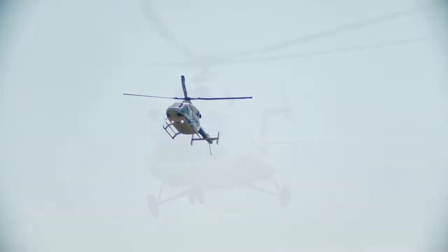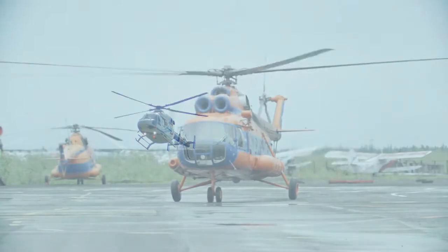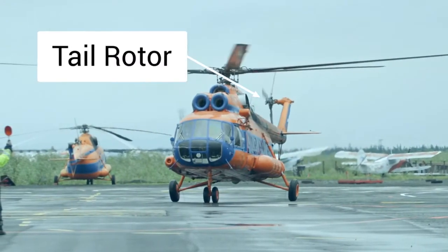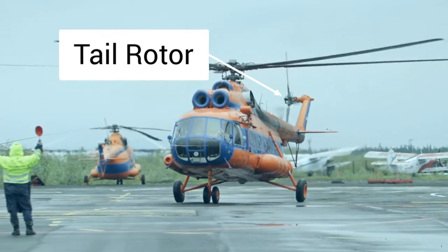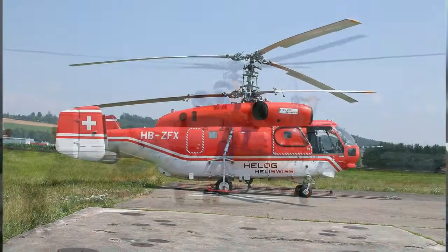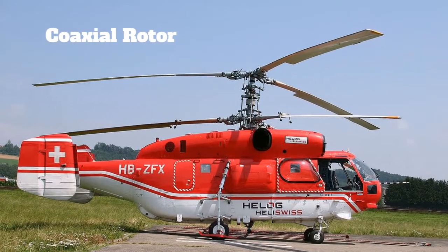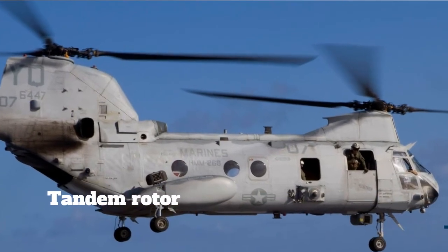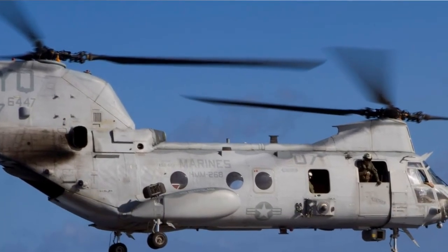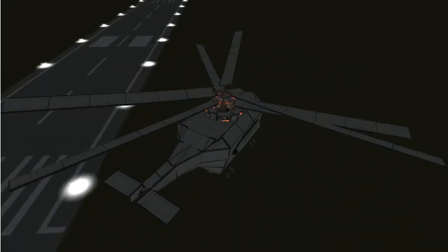While the generation of lift is similar, helicopters require an additional rotor to prevent them from spinning in place by the main rotor pushing the air to one side. Many designs use tail rotors to counteract this force. In other cases, designs may include coaxial or tandem rotors. Coaxial rotors are mounted in the same place as the main rotor, while tandem rotors are located on the opposite ends of a helicopter. In both of these designs, the rotor spins in the opposite direction to the main rotor to keep the aircraft balanced.